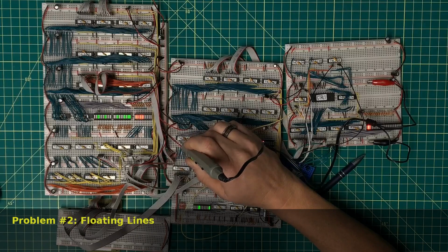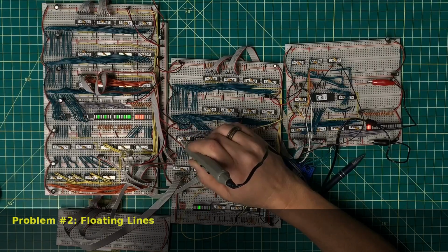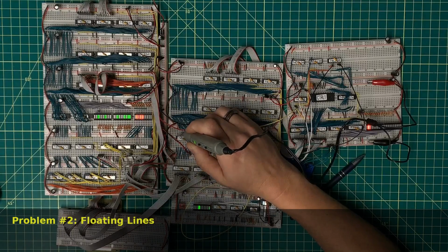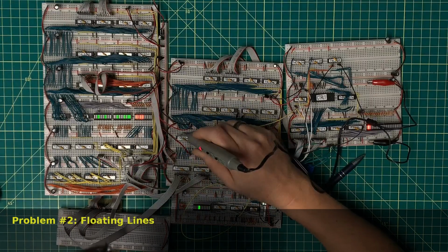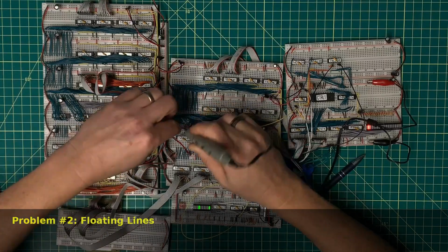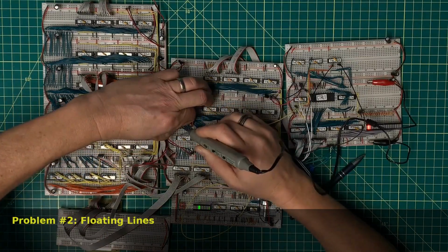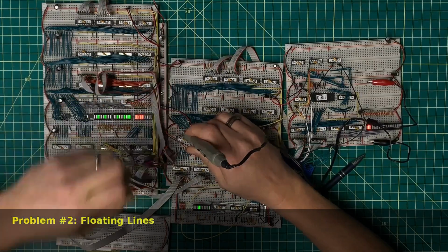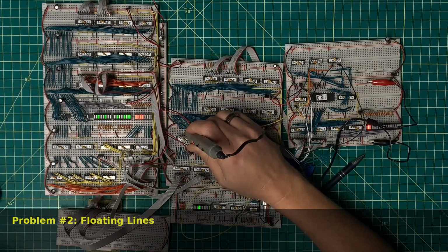So something's going on here, because I've got low, low, low, low, low, but I've got up here, low, high. So where could this be pulling high from? Let's see, it's all part of this node. Let's disconnect this and see what happens. That's low now. Oh, I pulled the wrong one.